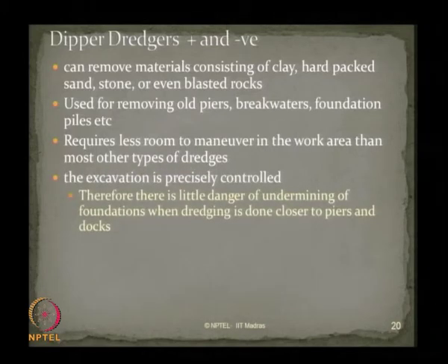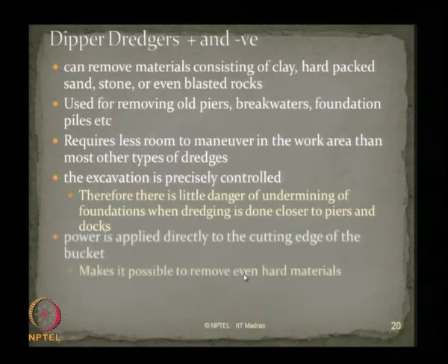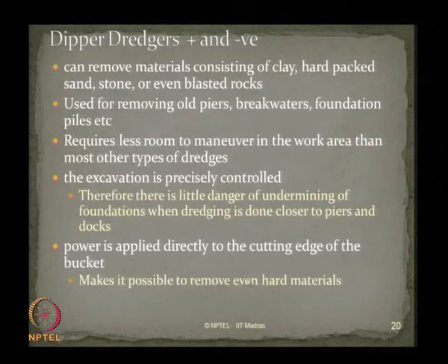The excavation is precisely controlled, therefore, there is little danger of undermining foundations when dredging is done. The power is applied directly to the cutting edge of the bucket, which makes it possible to remove even very hard material deposits.